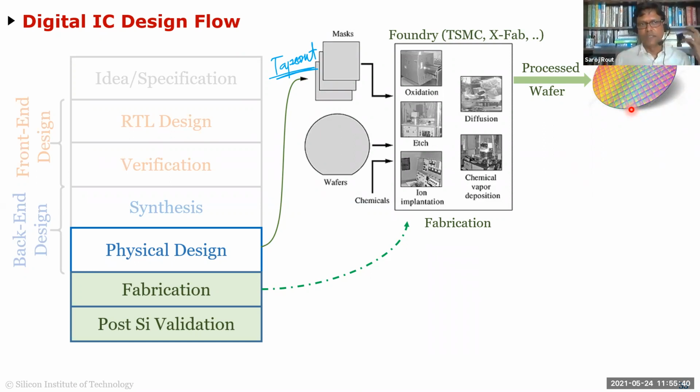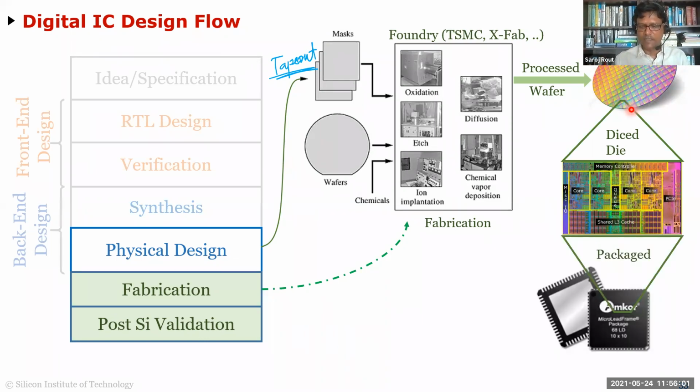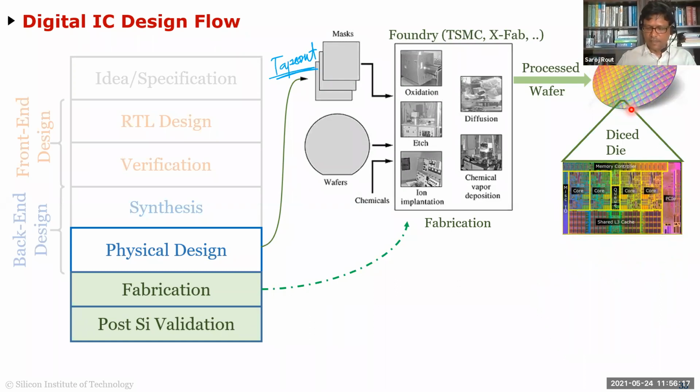But sometimes in chip manufacturing the packaging is very cheap, so they don't care. They say, no, just send it, we'll cut it and dice it, we'll test it at the package level, and if the part is bad, we'll just throw it away at that time. So for example, this is a die. This might be like 10 millimeters by 10 millimeters or something like that. Then you take it and package it into a package, like I said, and you have to connect all the pads to the leads, and then you can connect it to the outside PCB, as I'd shown.